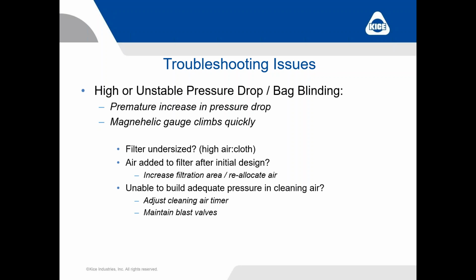Over time, we modify the systems we have. That's just a fact of life. We modify our systems to get them to a point that we need to operate, and sometimes that includes bringing more air or more dust, a higher concentration of dust, into a dust collection line. So ask yourself, what has changed? Has anything changed that's going to contribute to that shorter bag life or that faster pressure drop?